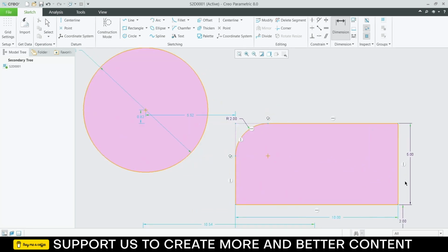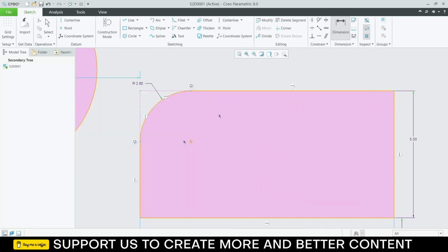Let's say you want to make a sharp cut, not the smooth one. So this is something called chamfer. So click on chamfer. By pressing Ctrl, select the two edges and notice I got the dimensions. Again, I want to edit them. So I'm not able to select it. Click on dimensions. Now double click on it. Give it a dimension as per your requirement.